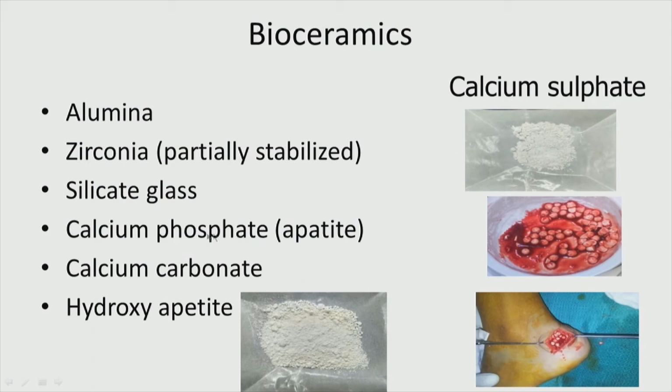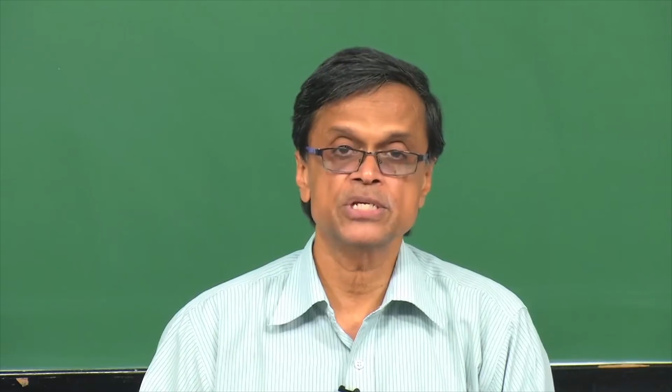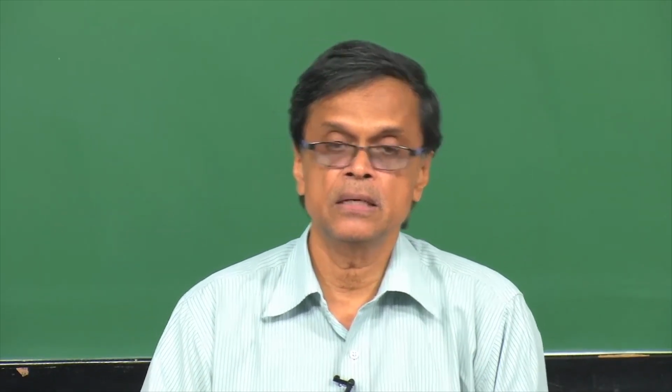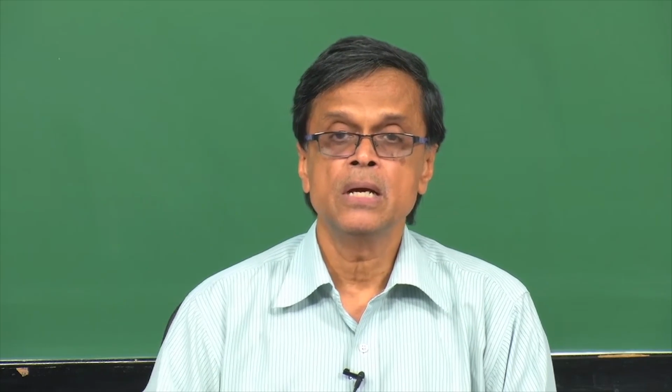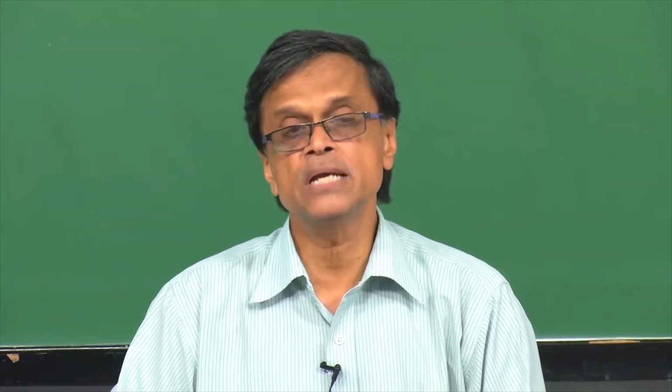So, these bioceramics are extremely biocompatible and they can be nicely integrated, especially in dental and orthopedic applications. Of course, they have certain shortcomings. They cannot take tensile force and they do not have crack propagation resistance. So, these are some problems of this type of material, but they have quite a lot of advantages which are now being exploited in the area of biomaterials. We will look at some of these in this particular class.